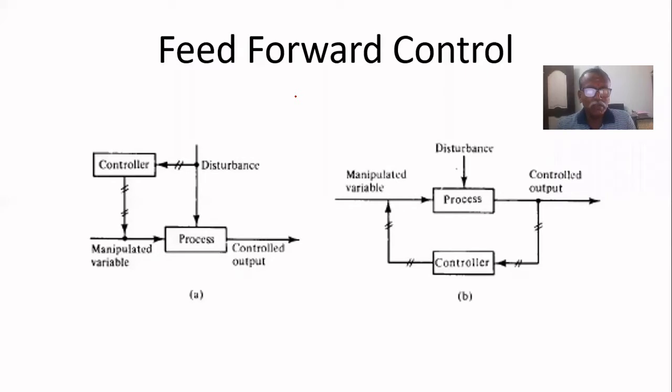Therefore, we cannot implement servo. It cannot be used as a servo controller. That's why we cannot use a feed-forward controller alone. It should be used along with a feedback controller. That is one of the reasons.